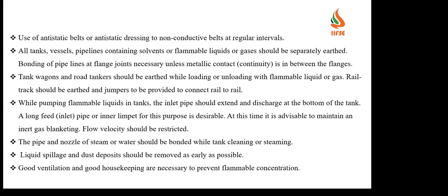Then the pipeline and also the nozzle of the steam or water should be bonded while tank cleaning and also steaming. Bonded in the sense that there also we have to provide earthing connectivity so that it will be eliminated. Then liquid spillage and also dust deposits should be removed as early as possible.